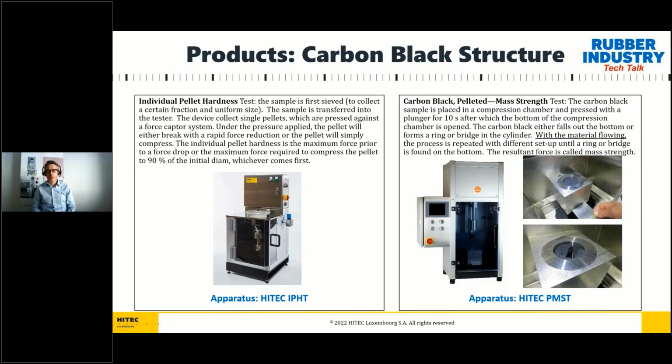Our equipment reflects more than 25 years of experience in the construction of pellet hardness testers, and this is the last version, which was released in 2018-2019. It is mounted on a damping table, which reduces the influence of industrial vibration on the precision of the measure, and is integrated with a sample carousel, which allows the operator to load up to 14 samples and measure them without operator intervention.